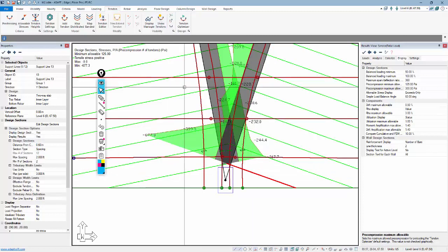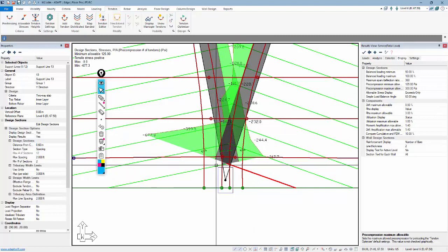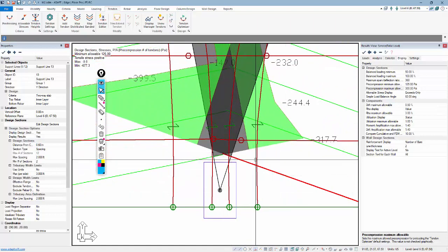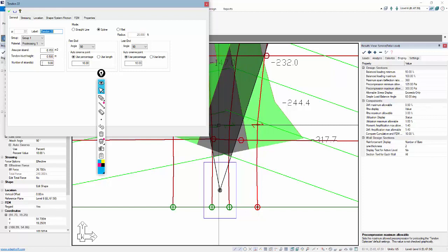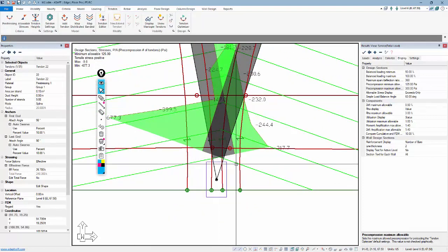Let me turn the tendons on. And we have a lot of tendons kind of passing through this joint. So this is really a function of how the strips are set up and how many tendons are kind of converging in this area. And if we look at this cut, we have 2 sets of tendons times 9 times 2. So there's 18 strands intersecting that cut.